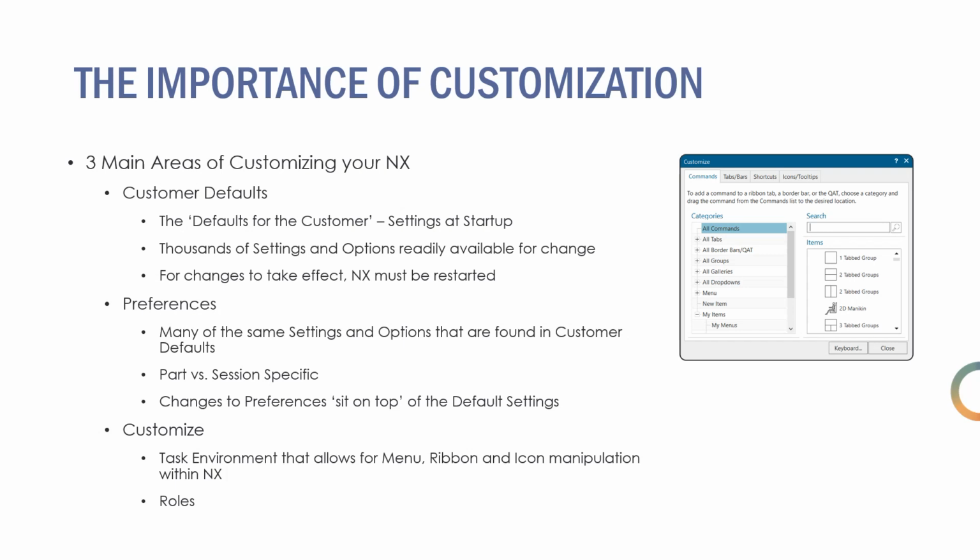Preferences are similar to what's available in customer defaults, but the changes take effect immediately and sit on top of the default settings. Some of these are part-specific settings. Some stay for the current session of NX until you restart, and then it'll look back at that default file. And others, usually those that deal with user interface, will stick from new NX session to new NX session.